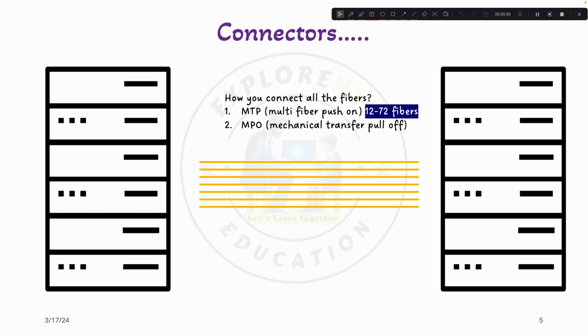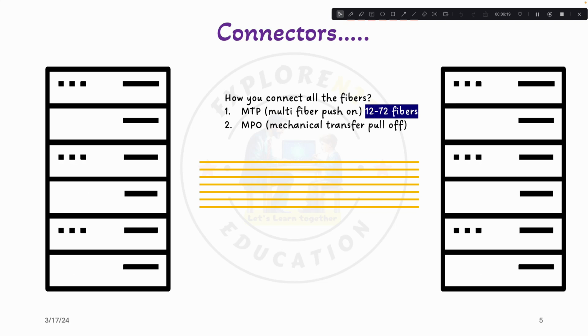Handling these fibers is very difficult. But that's how these connectors come into the picture: the MTP and MPO connectors. MPO is the basic connector, and from MPO, another connector, MTP, evolved. MTP is basically a brand name, called US Conec, which comes from MPO. It's more flexible than MPO, and it's used in high performance environments. High durability. That's the difference between MPO and MTP.